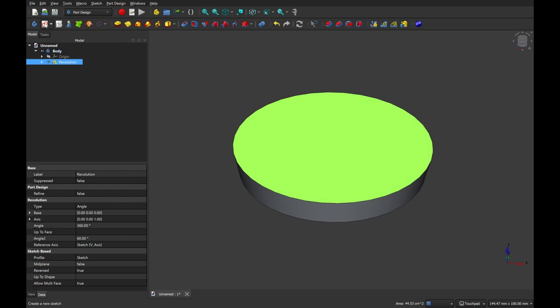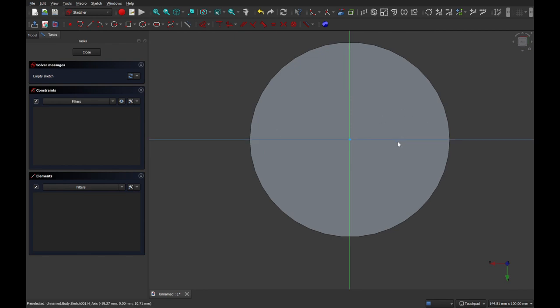Now, let's say we want to do the pockets either side of a handle. So, select that face. We'll do these two pockets. Now, because we've gone around the vertical axis, which is the simplest way to do it, we can utilize either the center point, or we could select external geometry, which would import the center point, but the center point exists. So we'll just get rid of that external geometry. Right.